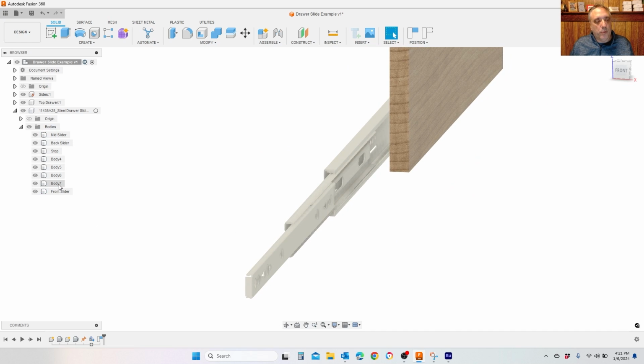The one thing with these bearings, we don't need to actually have them be separate components because they're just sitting still where they're at. We're not actually going to show the bearings rolling. I'm pretty sure that those bodies aren't even constructed correctly to do anything with. So we just want to find these bearings, and we're going to end up just pairing them with the appropriate slider. Call it bearing 1 through 4. Okay, so I have those bearings, and if we click on these, it looks like 1 and 3 would go together, and 2 and 4 would go together.